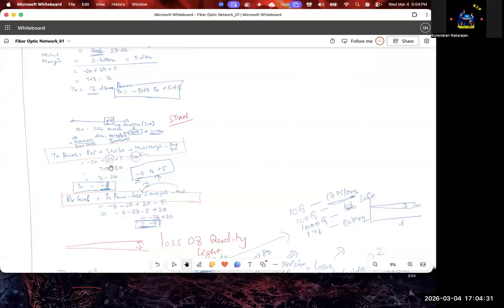This is how you tackle it even in interviews. If you know what is inside the formula, then you can tell. For example, if I ask you how you decide the transmit power, you can say transmit power depends on the RX sensitivity, total loss, and maintenance margin. Is there a dependency on RX sensitivity?